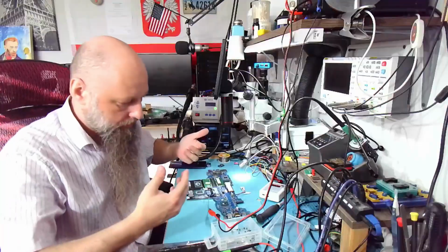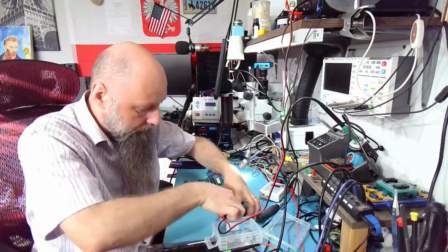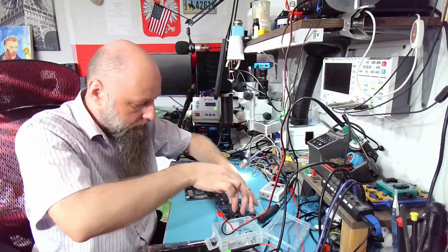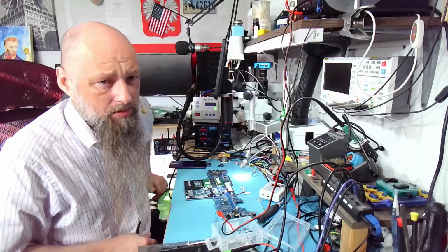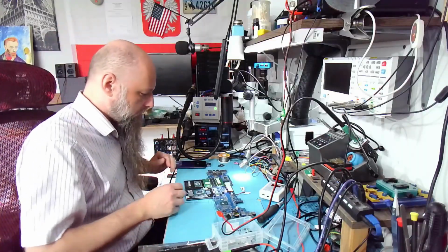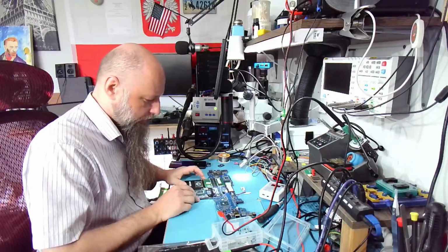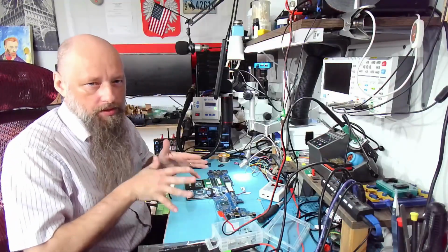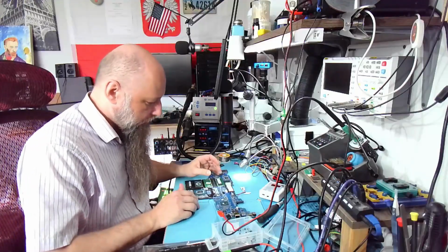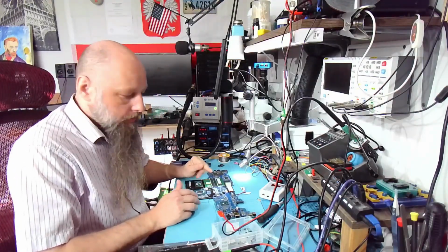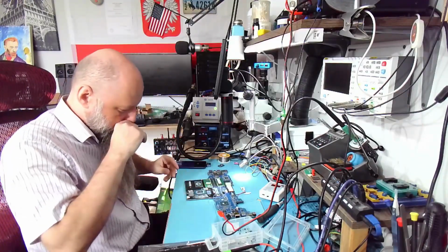So usually when that happens, from my experience, it's usually the VRM, because they dissipate heat very well. I mean, it still could be the core, but I think at 400 milliwatts we should see the core light up. So the power is going somewhere else, and it's usually the VRMs that are responsible. We could desolder the coils, but we shouldn't have to.